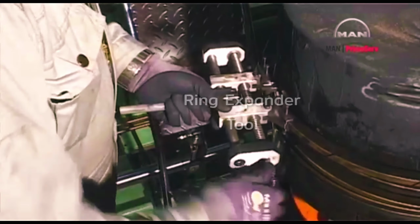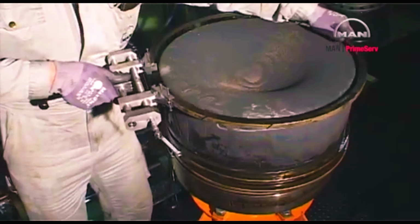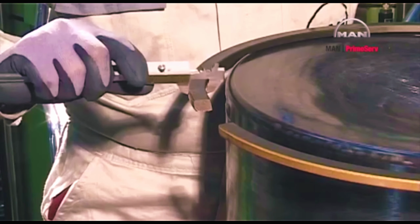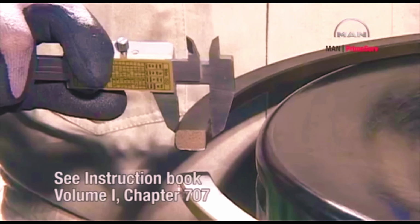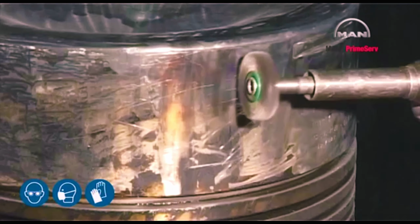Take off the piston rings by means of the ring expander. Clean and inspect the rings and measure the radial width of the rings. Note down the results. See the instruction book, Volume 1, Chapter 707. Clean the piston crown.